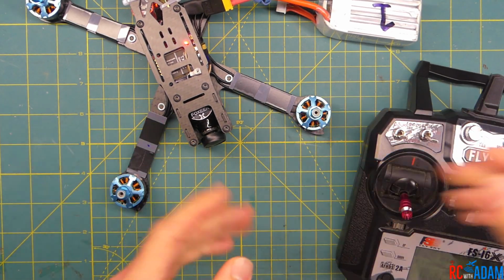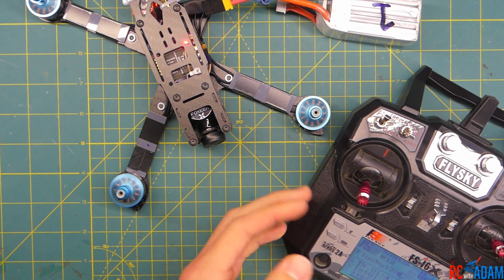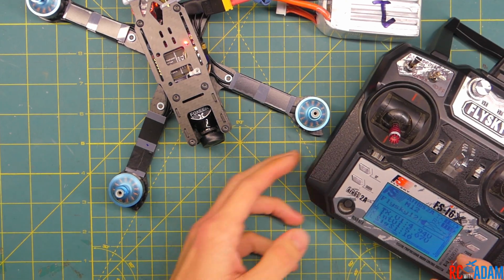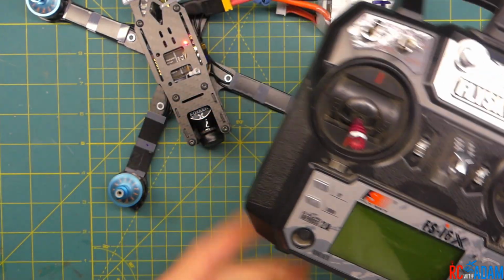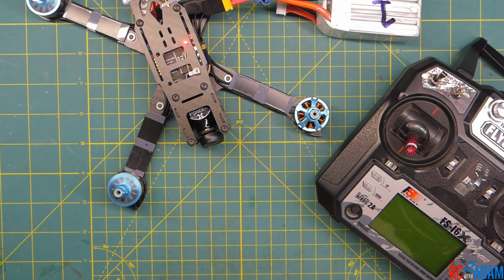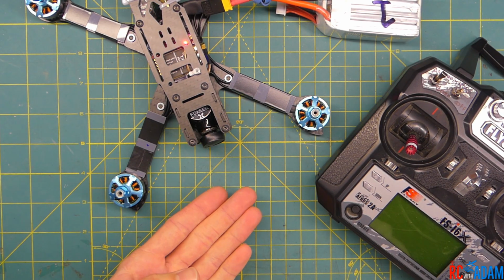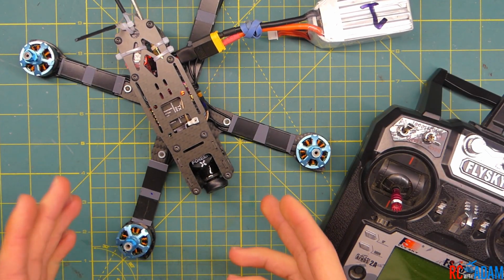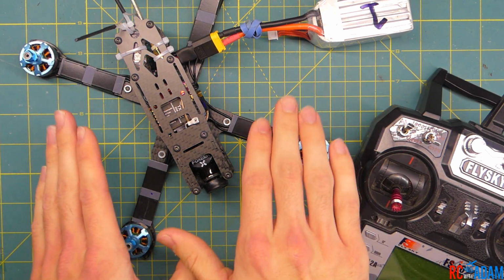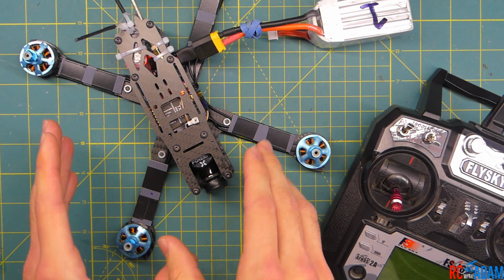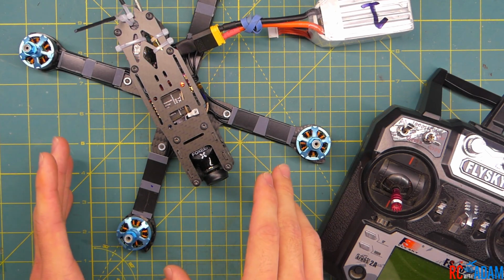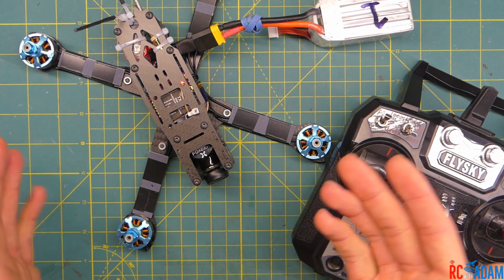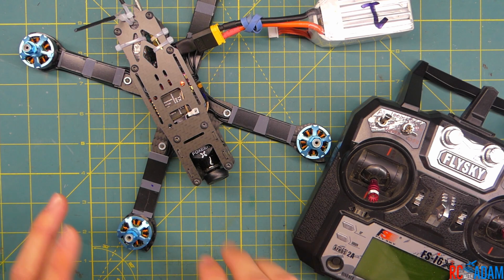And then let's check the failsafe. What we're going to do is raise the throttle a little bit, and then I'm going to shut the transmitter off. Okay, and then you can hear, there we go, and it stopped. The reason it took so long to do that was because I had set mine to land, so I set a delay on the shutoff time, basically. If you leave it at default, it should just shut right off after maybe 3 seconds max. So that's just how I have mine.